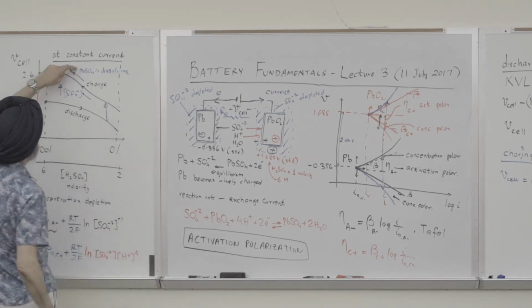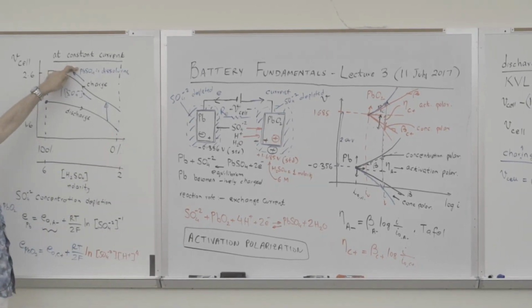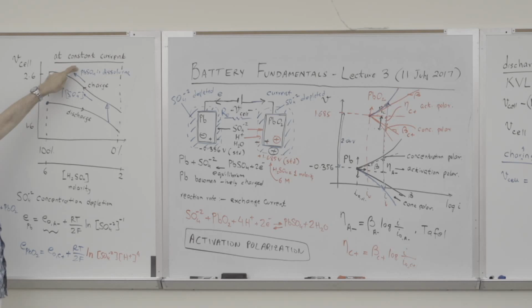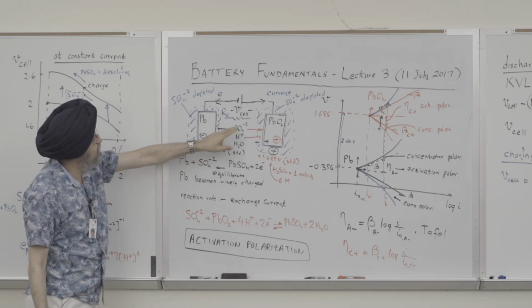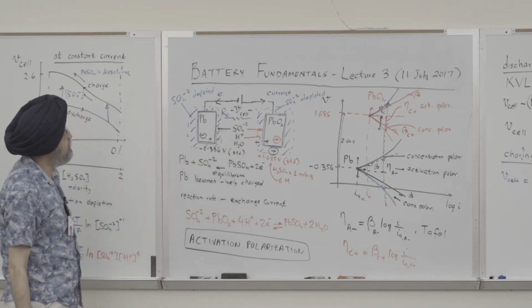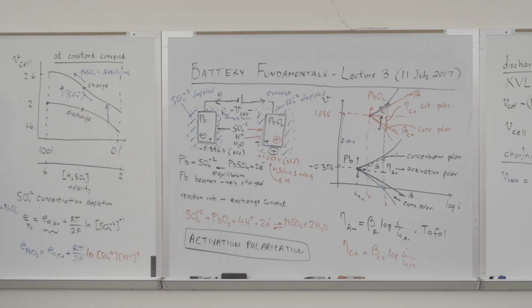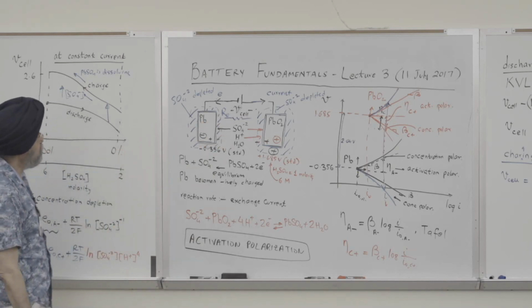So this is the resistive element. So you're removing a resistor from the circuit. So instead of the voltage dropping across this lead sulfate resistive element, it is dropping across the V. So basically you remove a resistive element in series with this charging source.